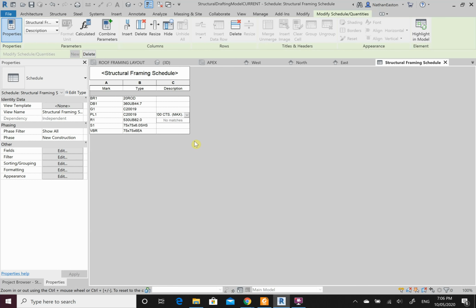And we have, I think it was, 2 M16 bolts with an 8mm cleat plate, and we have 3 rows of bridging. Okay.